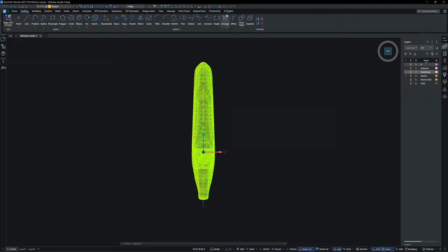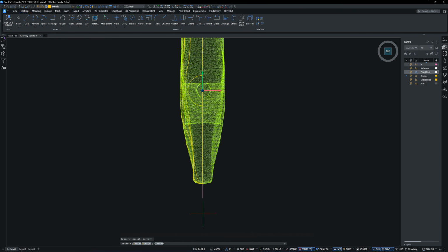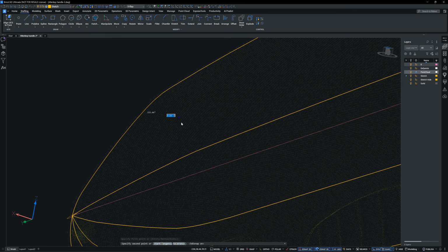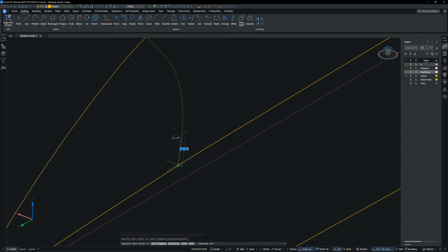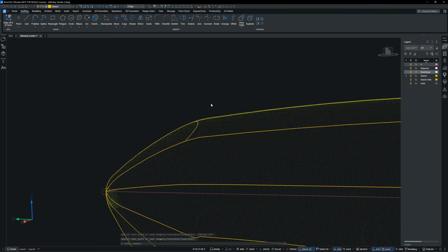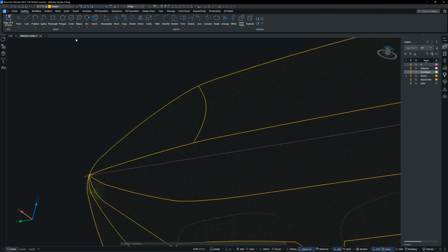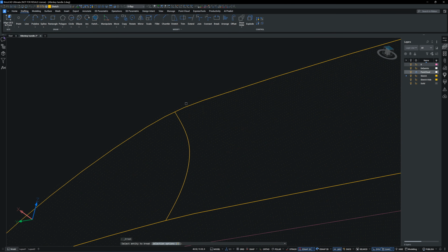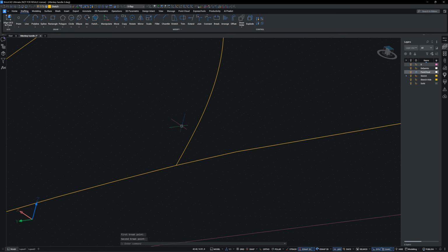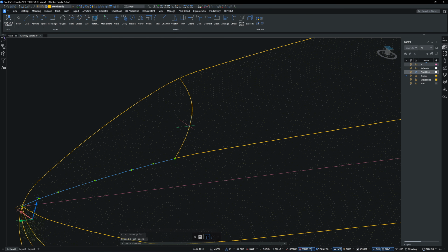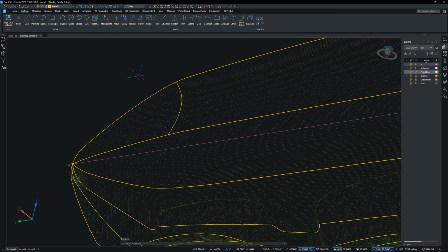Now I have enough 2D sketches to create the surface boundary. There is a simple rule. A surface should be created in smaller segments, divided at the locations where the curve changes. I will use the spline to close the boundaries between the 2D sketch lines, snapping the spline control points directly on the point cloud.